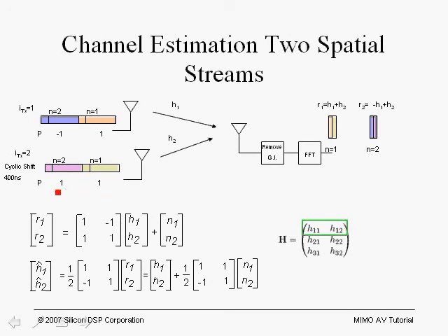The reason for the cyclic shift is that unless we do a cyclic shift, these two symbols are the same, and when they're transmitted simultaneously from transmit chain number 1 and transmit chain number 2, they're received at the receiver, and you have possibilities of constructive and destructive combinations which are detrimental to the signal. By adding the cyclic shift, we actually have a diversity gain, and we have an improvement in performance.